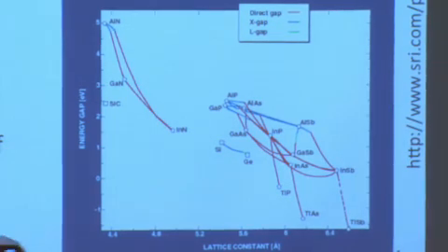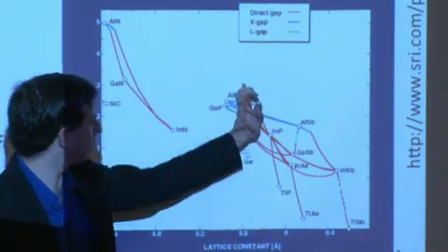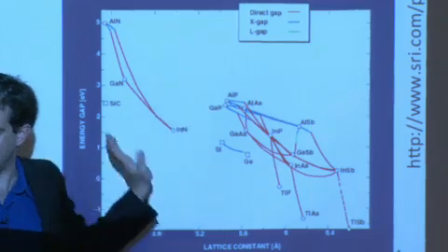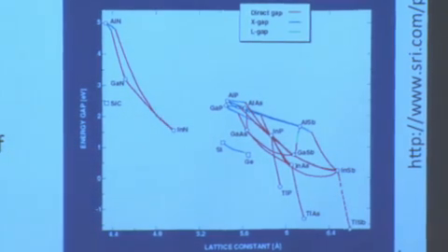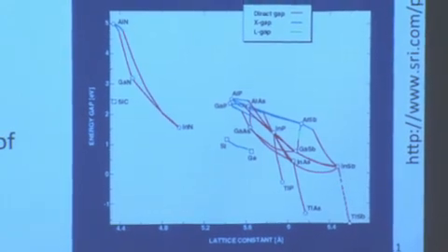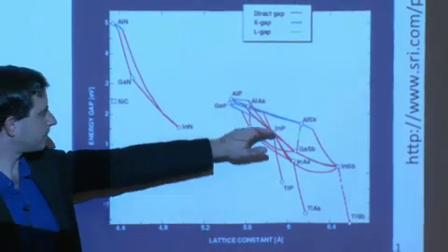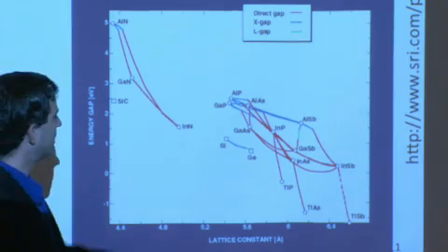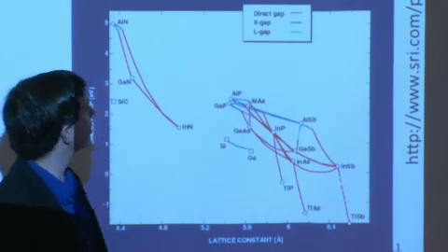And so you need to make sure that the materials that you grow are matched in lattice constant, but varying in bandgap if you're trying to grow a multi-junction device, if you're trying to grow a very high efficiency solar cell device. And so the growth or matching of materials one on top of another is important, especially for the multi-junctions, also for some of the single junction materials if you really want to minimize the interface recombination.